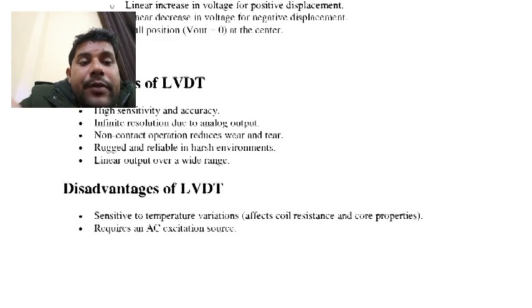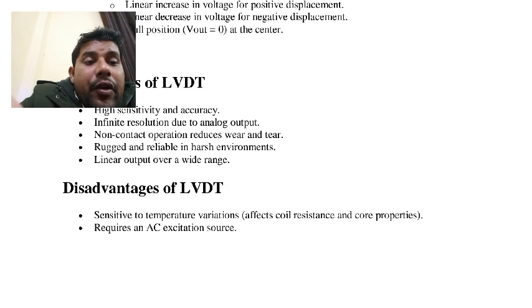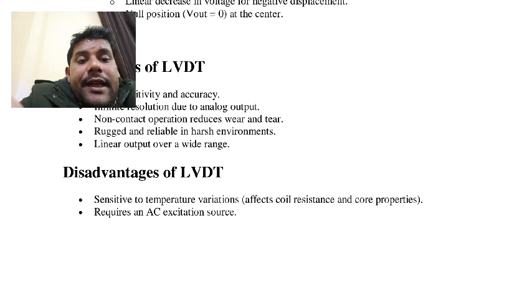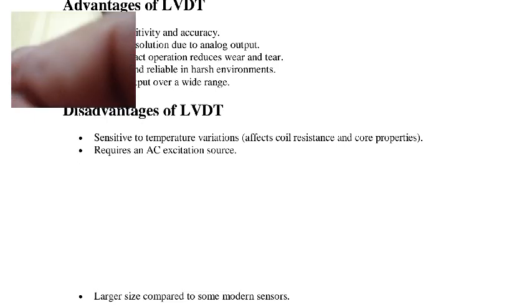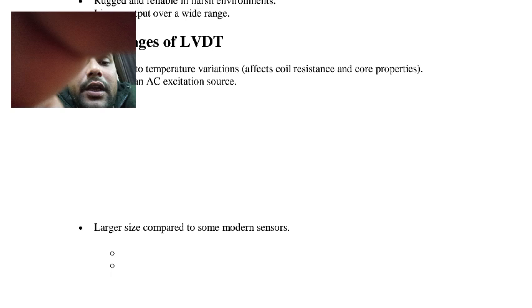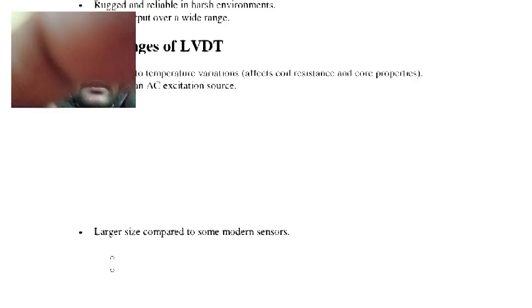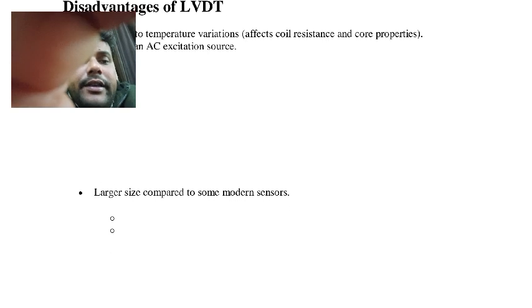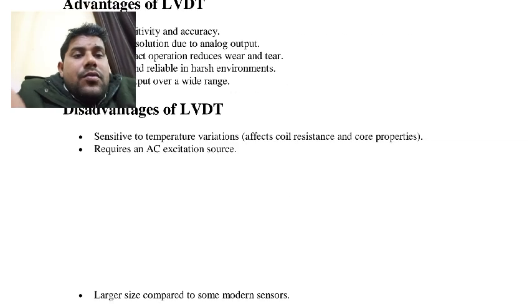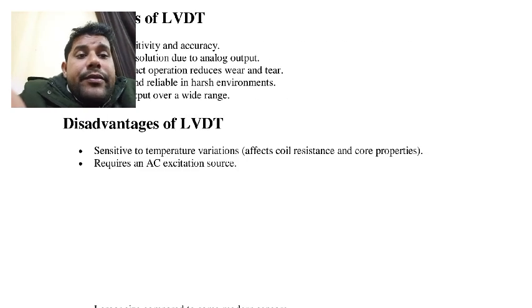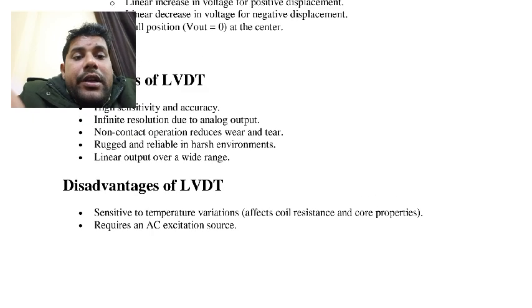Disadvantages: sensitive to temperature variation, which affects the coil resistance; AC is required for excitation; and large size compared to some other sensors.